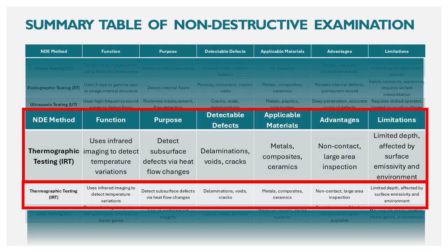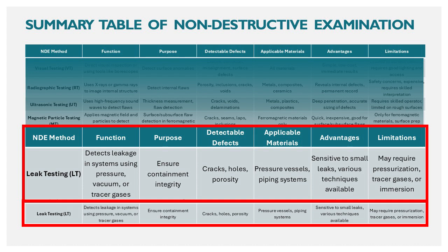The advantages of infrared thermography testing include being non-contact and fast, and being able to inspect large areas. The limitations of infrared thermography testing include limited depth detection, being affected by surface emissivity and environment, and requiring thermal contrast.